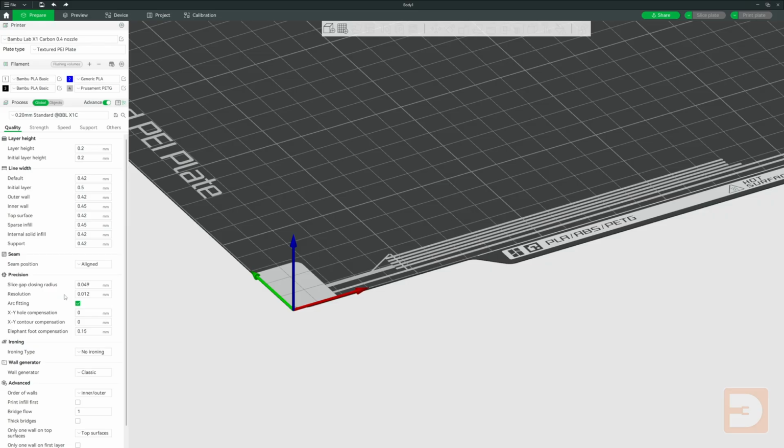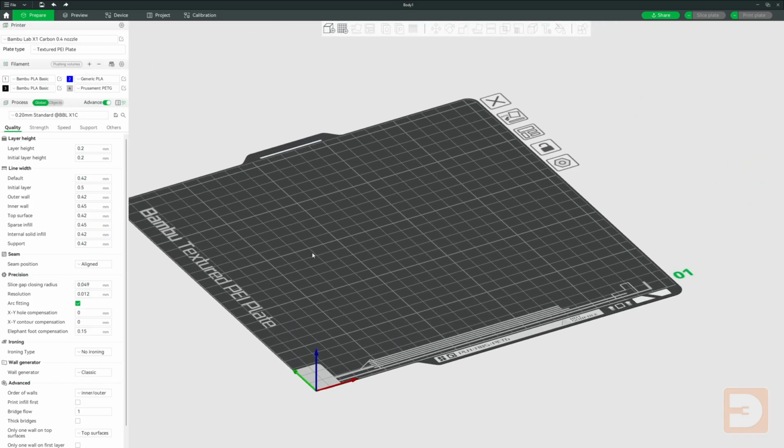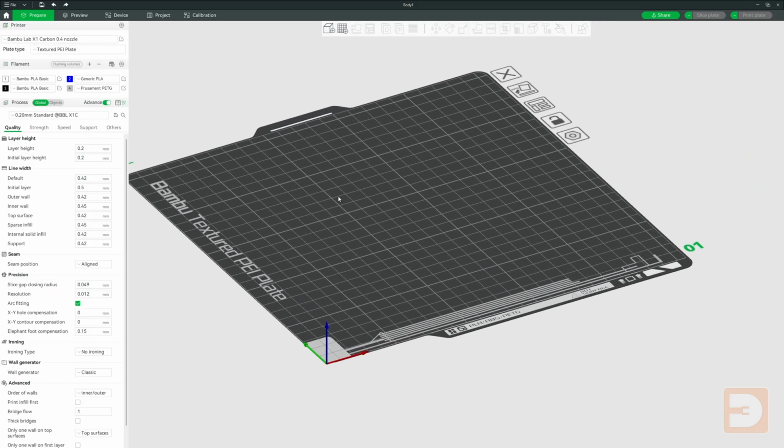This makes it much faster to slice as it's not generating command lines for movements that would be imperceivable or even detrimental to your print. Arc fitting is a really cool feature which can both speed up your print and in many cases improve the quality, or at least it would do if it wasn't for the fact that you were probably already using it, because usually this is set by default to on.